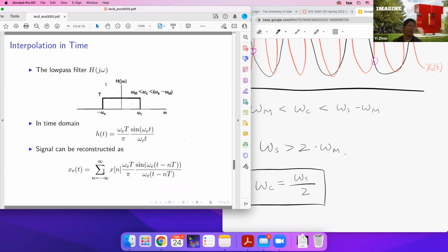Okay, think about this equation. You have your discrete samples x[n] queried from that continuous time signal. And how do you reconstruct the underlying signal? Well, at each discrete sample x[n], you will need to multiply it by such a sinc type signal. Or you can understand this as a sinc type signal shifted to the location nT.